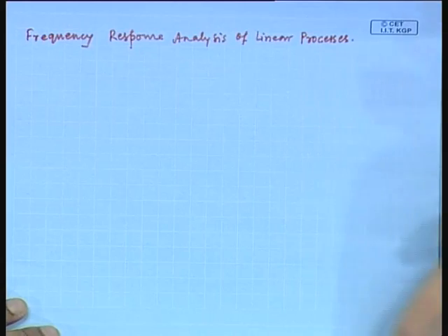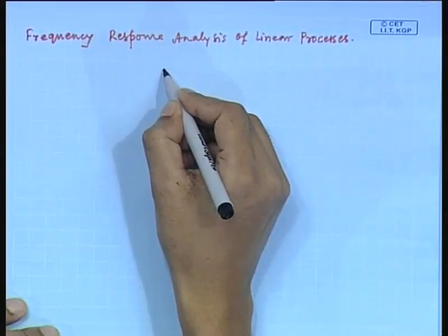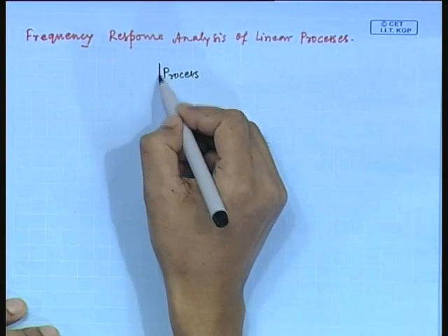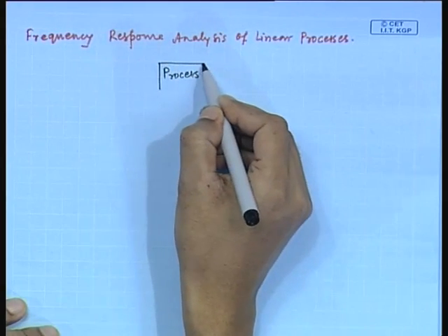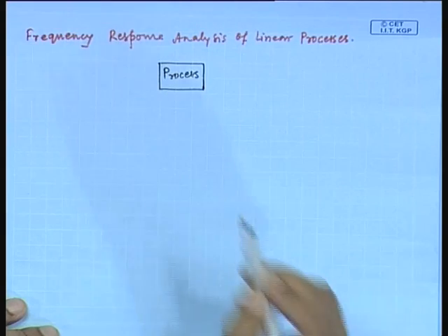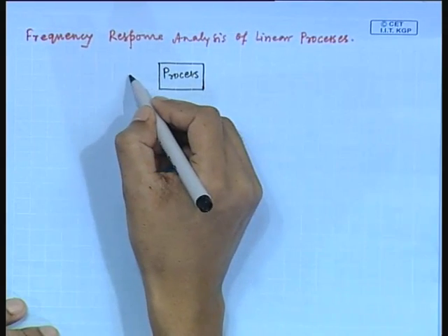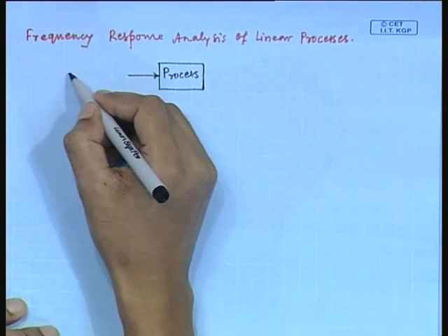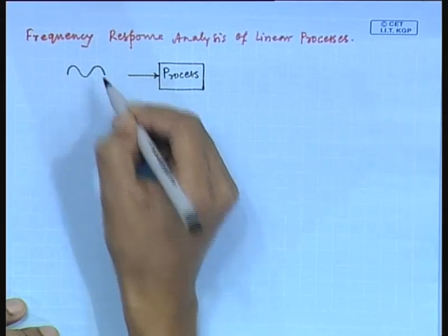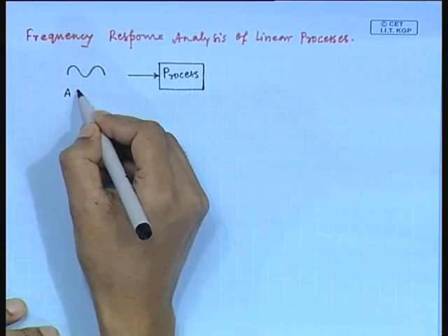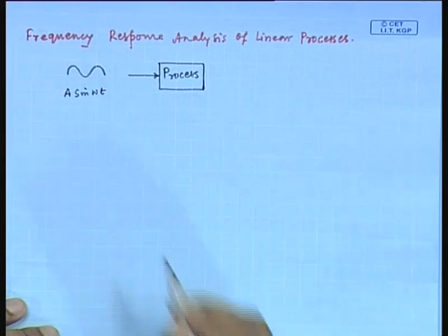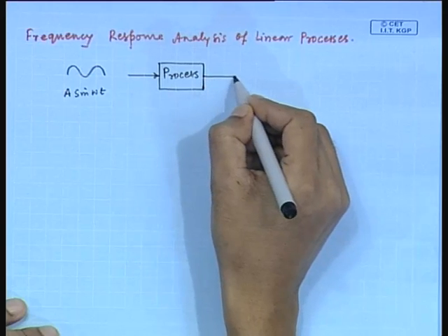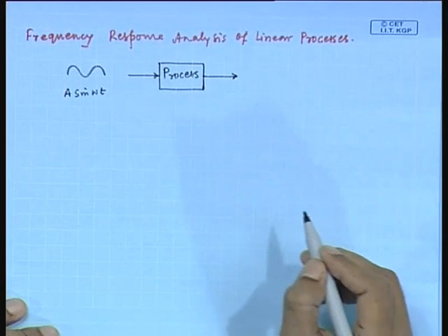So, we need to consider a linear process. When the linear process is subjected to a sinusoidal input, its ultimate response after a long time is also a sustained sinusoidal wave.